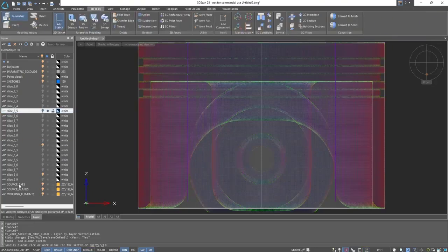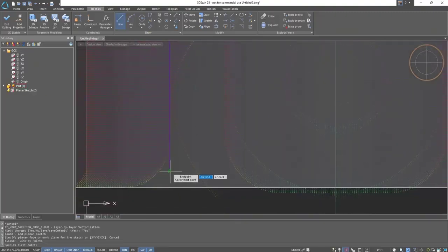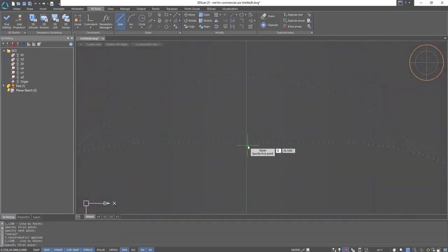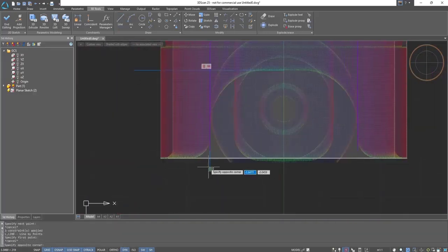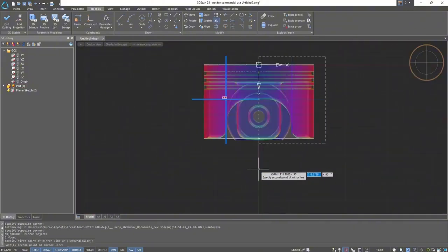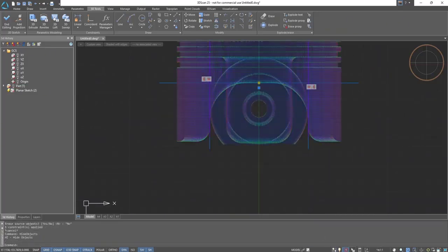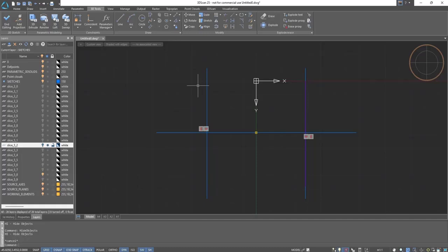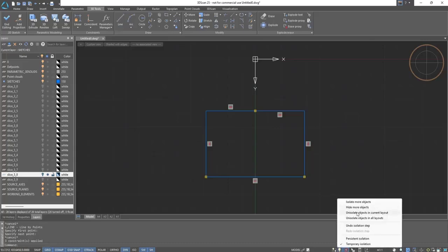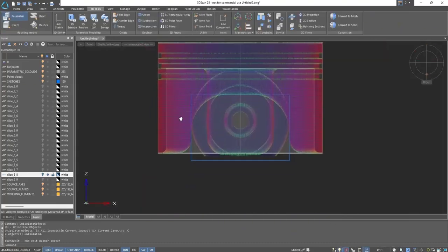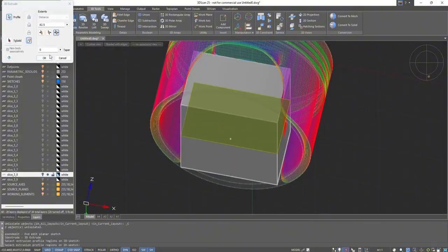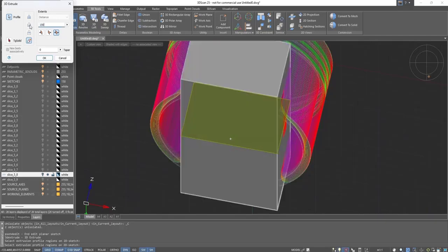Let's create a new sketch and draw the lines that will now show the outline, and then clip and mirror them. We will perform contour extrusion, taking into account that this will be integrated into our existing body and the cutting function will be used.